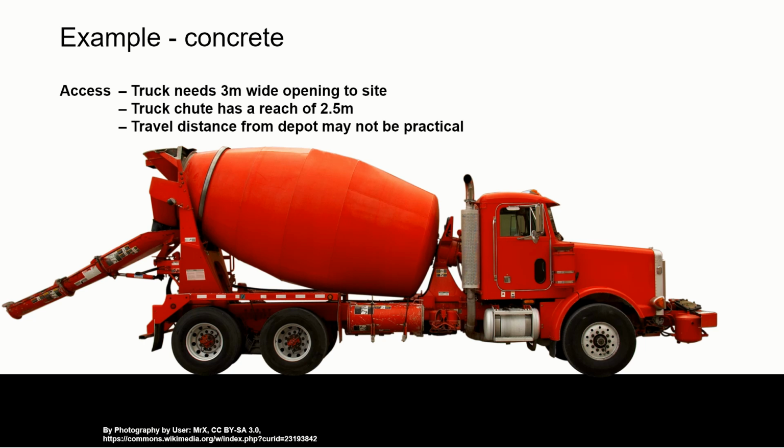In extreme cases, it might not be practical to design concrete in a building because of the distance from the depot, in which case you would have to spend additional money on bagged concrete, dry mix concrete, which would then be mixed up on site, which is labour intensive, would probably add cost, complexity, maybe even reduce the quality of the concrete. So the overall distance from a site to the nearest available material centres is an important consideration.